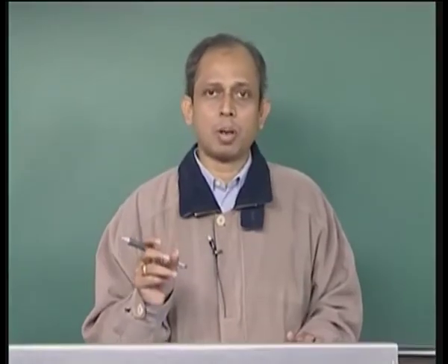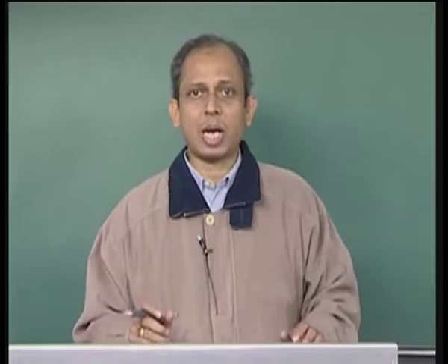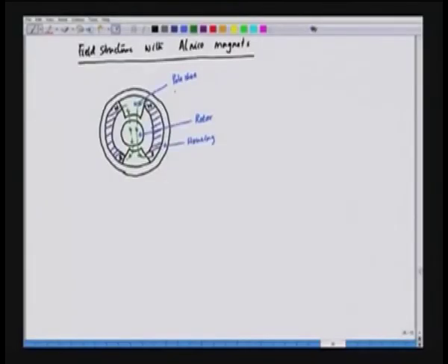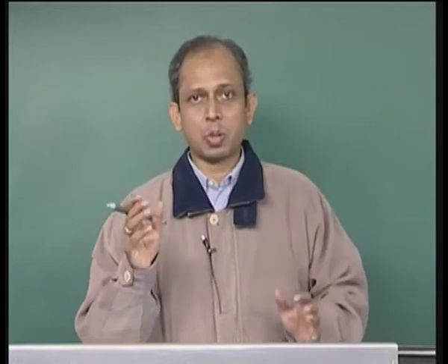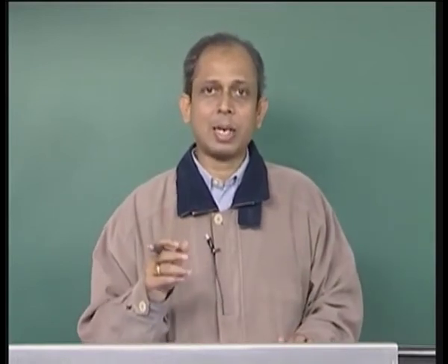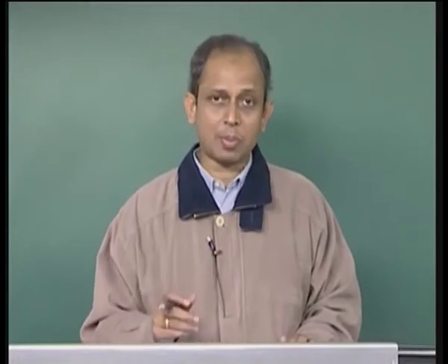Now, in all permanent magnets, we should remember that the permanent magnet materials are very brittle and they cannot be easily machined. This gives this kind of long magnets which can be fitted in the soft iron. So, the pole shoes are basically soft iron and the magnet is long and a little curved, and the magnet is fitted in the armature, the stator housing with the pole shoe, so that ultimately it creates north pole and south pole, as we have seen.